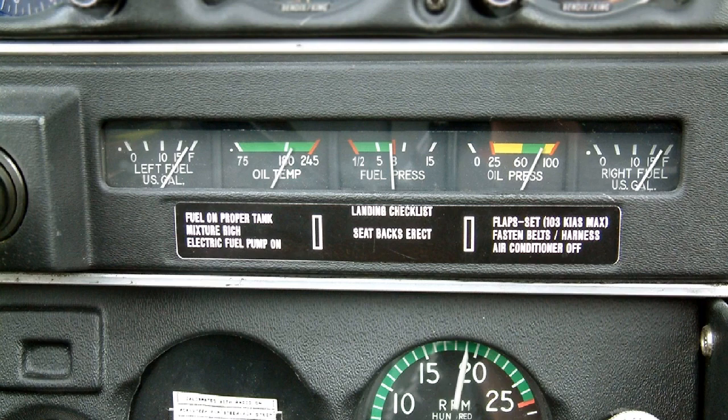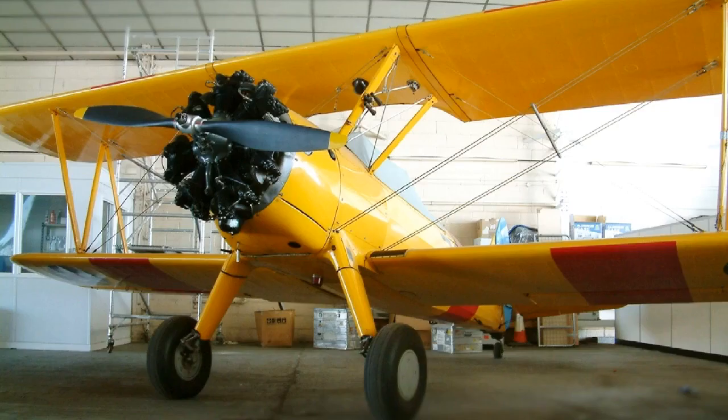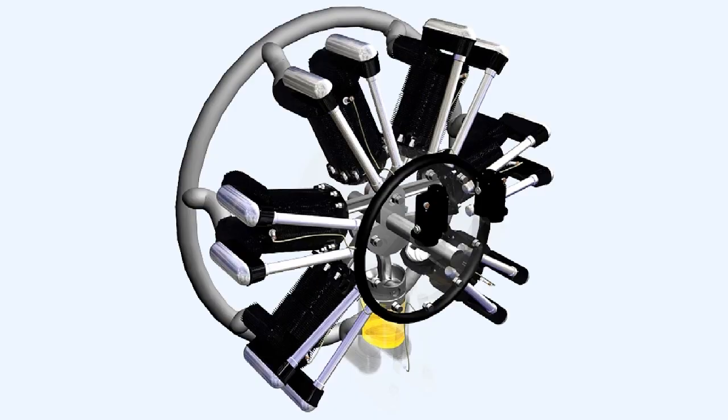Indications of oil pressure and temperature give the pilot a good idea of the mechanical integrity of the engine. Of course, the pilot must then interpret these indications correctly. Aircraft which use radial and inverted engines require the pilot to have knowledge of the lubrication system even before he starts the engines. Both of these types of engines can suffer from a problem called hydraulicking. In radial and inverted engines, oil may accumulate in the cylinders at the bottom of the engine, between the piston and cylinder head after shutdown.